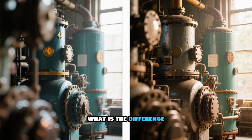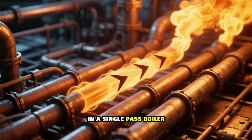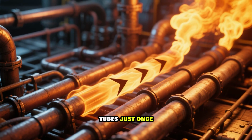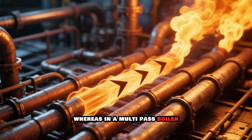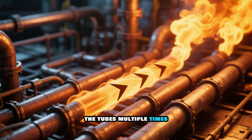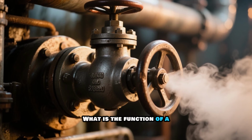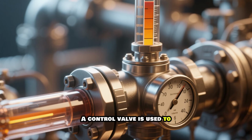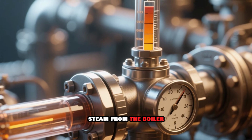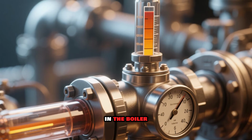What is the difference between a single-pass and a multi-pass boiler? In a single-pass boiler, the flue gases pass through the boiler tubes just once, whereas in a multi-pass boiler, the flue gases pass through the tubes multiple times, increasing the heat transfer efficiency. What is the function of a control valve in a boiler? A control valve is used to regulate the flow of steam from the boiler. It helps maintain a constant pressure and temperature in the boiler.